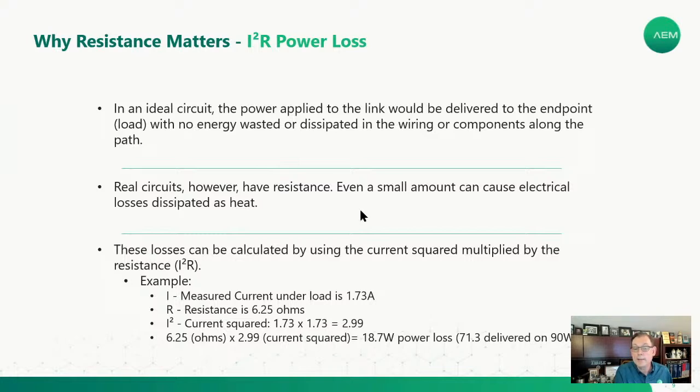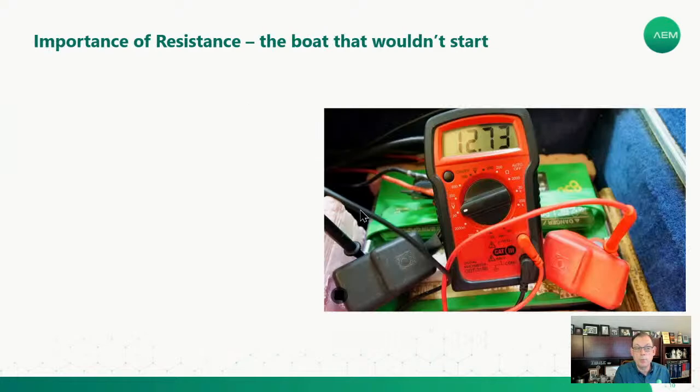When we look at the allocated power, which is the theoretical number that we can get at the end of that link of 4-pair cabling, that's where we come up with the 71.3 watts. And again, this 6.25 would be if we had 25 ohms of loop resistance on each of the pairs, and then that boils down to essentially 6.25 ohms.